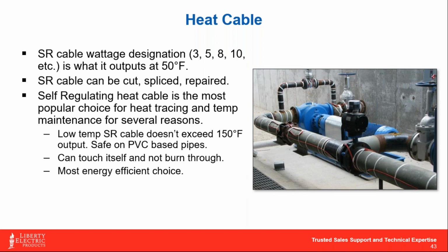So when we talk about self-regulating cable, it gets its name because this cable is able to expand and contract based off the surface temperature of what it's up against. And that's how it throttles its heat output up. So there's a standard within the industry, and when we designate a heat cable as, say, a 10 watt a foot cable, that's what that cable's emitting at 50 degrees F. And the colder it gets, the higher that wattage value is going to be. And the warmer it gets, it really doesn't cut back much below what the rated duty is, and that's just due to the construction of how these cables are made.